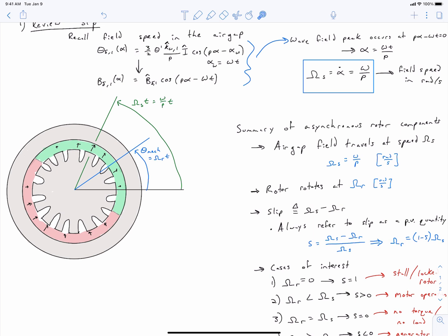And when you install a rotor winding in here, you can design it much the same way as you would design a stator winding. And then you either short circuit the connections, and so in that case, that winding behaves a lot like a squirrel cage rotor would behave. Or you could connect its phase connections via brushes and slip rings out to the stator and manually inject currents into the rotor.